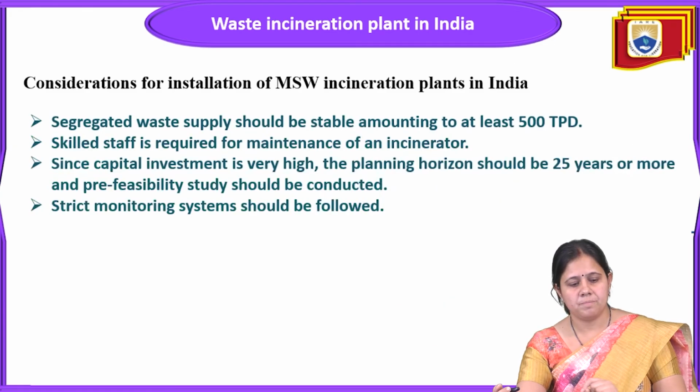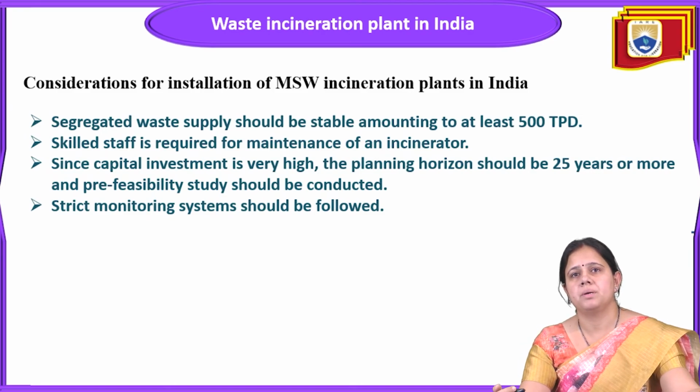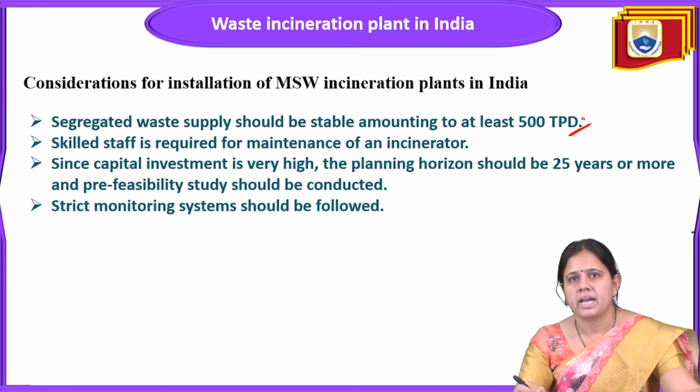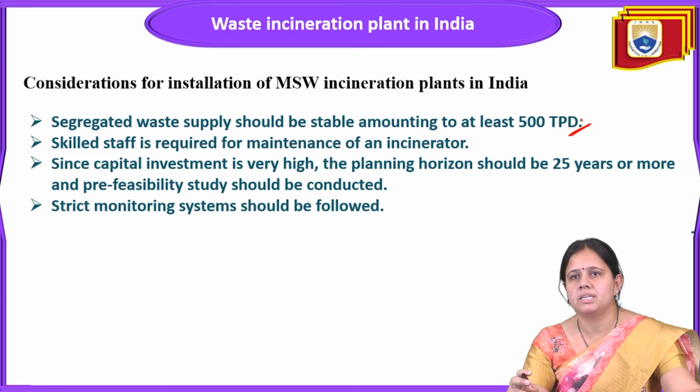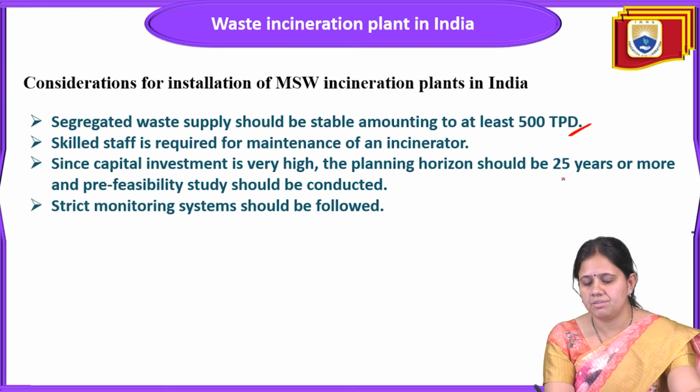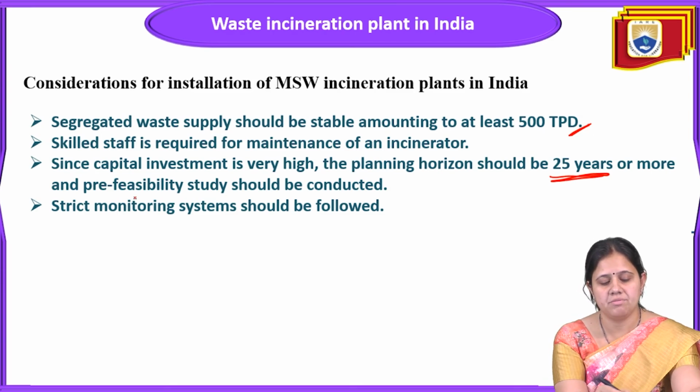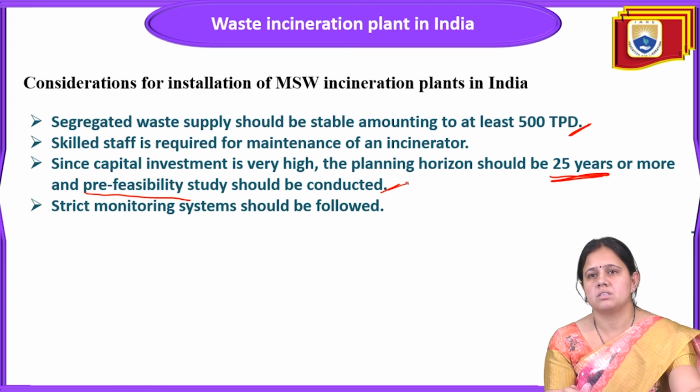Next point: segregated waste supply should be stable, amounting to at least 500 TPD, and skilled staff is required for maintenance of the incinerator. Since capital investment is high, the planning horizon should be 25 years or more. A pre-feasibility study should be conducted, and a strict monitoring system should be followed.